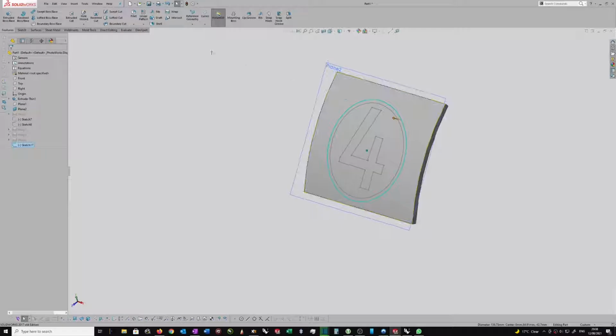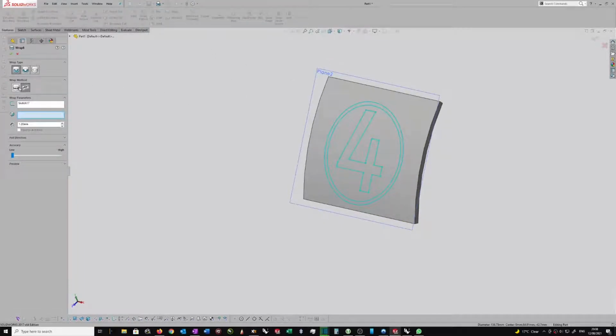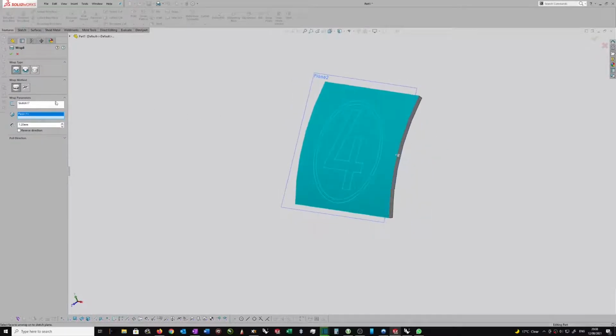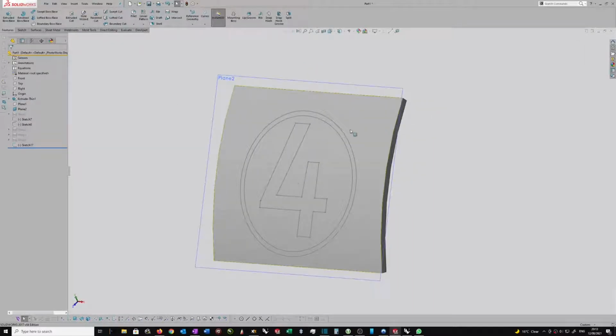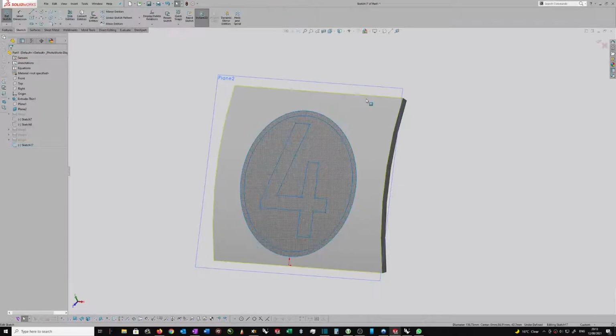All right, now I'm going to try wrapping. So select the sketch, say wrap, and select that face, and you'll see it won't do anything. Doesn't matter what you do, it's not going to give you a nice yellow line. So if I say yes, it says there's a problem from intersecting open contours. Question is, how do we get one item to be on top of the other and locate them properly in two separate sketches? So I'm going to go back to the sketch, edit it.